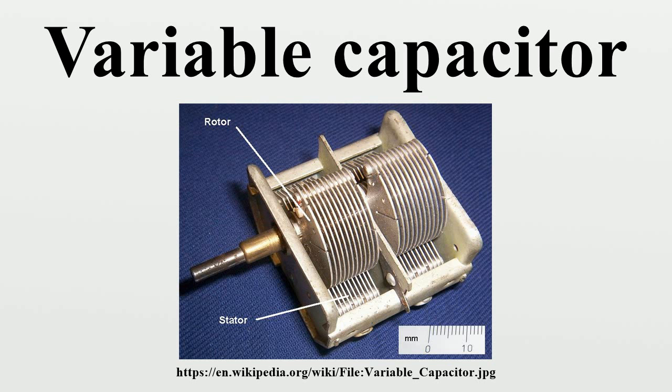Butterfly. A butterfly capacitor is a form of rotary variable capacitor with 2 independent sets of stator plates opposing each other, and a butterfly-shaped rotor arranged so that turning the rotor will vary the capacitances between the rotor and either stator equally. Butterfly capacitors are used in symmetrical tuned circuits, e.g., RF power amplifier stages in push-pull configuration or symmetrical antenna tuners where the rotor needs to be cold, i.e., connected to RF ground potential.